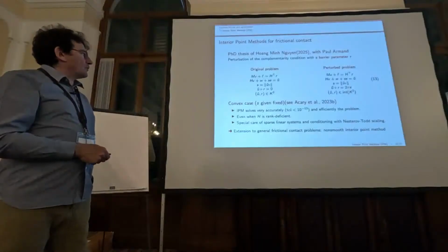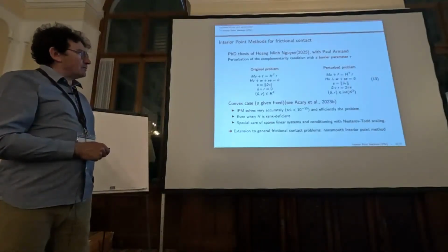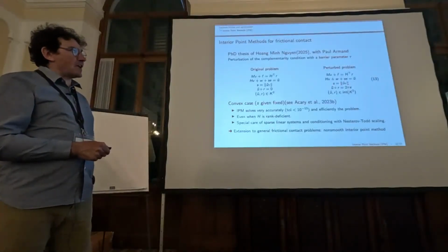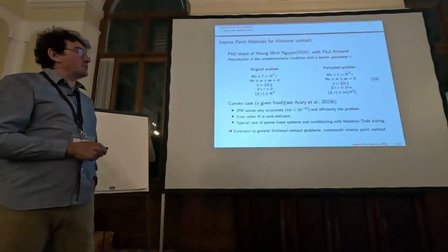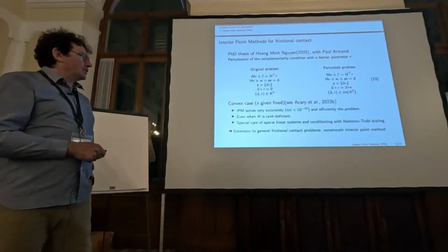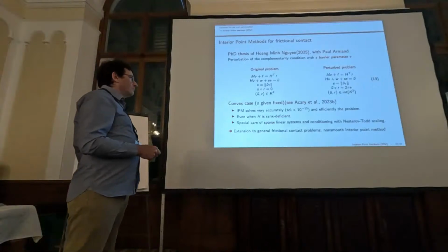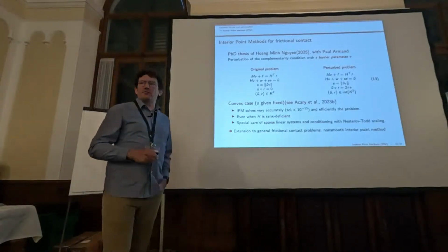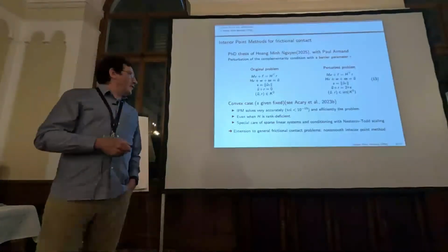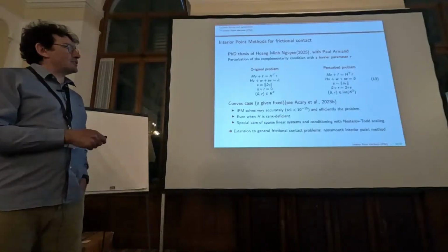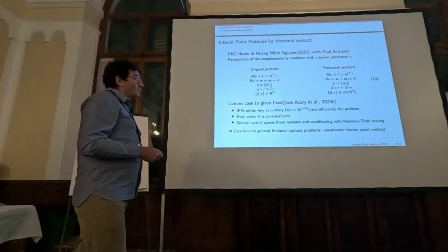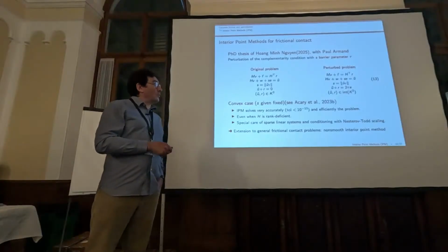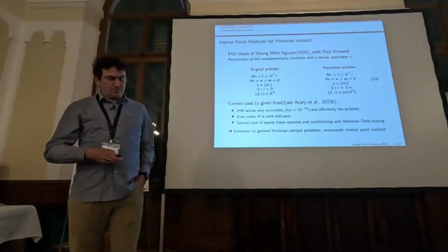And in the convex case, for instance, if S is given, so fixed S, this problem is in fact the optimality condition of a convex problem. Interior point techniques work quite well, very efficiently. We get second order convergence. Even if H is rank deficient, this problem is well posed. So now we will try to extend that to the general frictional contact problem when S is not fixed.